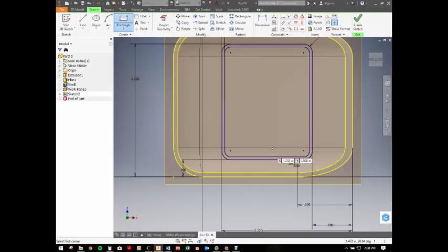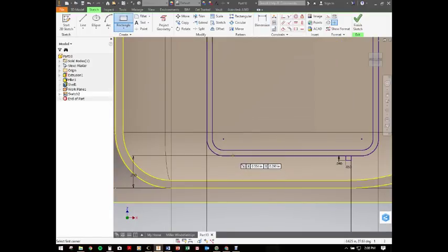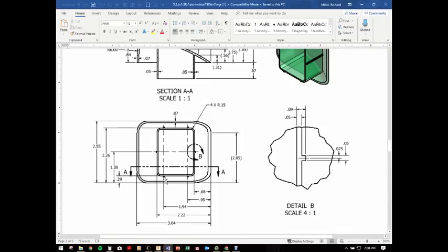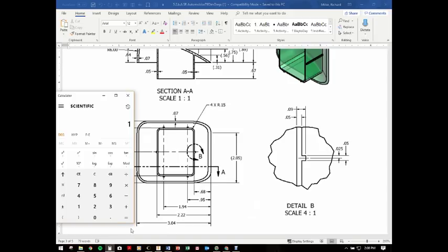All right, we'll do it again over here. Same rules apply. Make sure you don't catch that dimension. And then again, it's 0.05 by 0.04. And this time my datum is 1.94 minus 0.025 is 1.915.